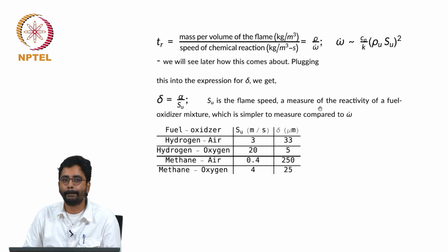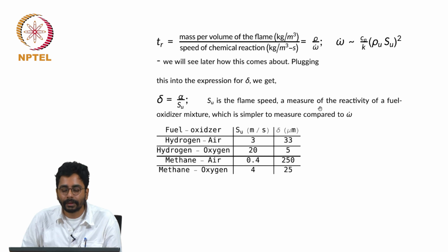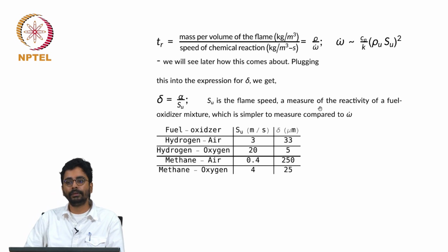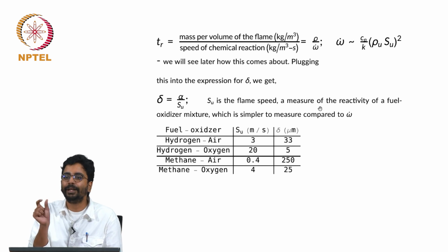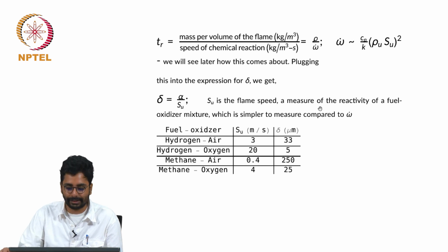Here, the elements which you have considered, we have said that the flame has two zones. One is the actual flame zone where the temperature is very high and the reactivity is high, and the peripheral zone where the reactivity goes down and relatively the temperature goes down. So we are considering homogeneously similar elements across the entire region. Where the fluctuation is higher or where the drop is drastic, are we not supposed to take finer elements to capture that? That is correct, and that is the reason why we are estimating the thickness of the flame, so that the volume that we choose is not much larger than that, so that we are homogenizing it. Yes, the assumption of homogeneity is maintained.